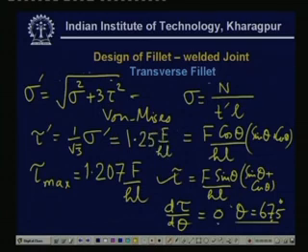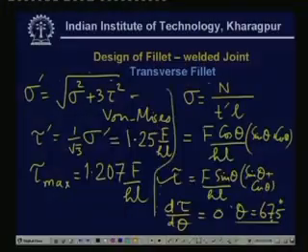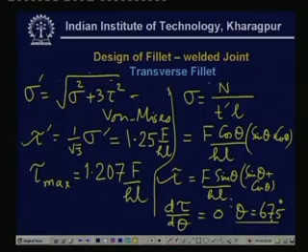So, this I leave to you to calculate, but what is important is that having done all this, what we get is the average value, but it seldom matches with the experimental results. Experiments were carried out with a photoelastic apparatus, and it was found that it is very difficult to find any match, that is, there is practically no match between the strength of materials approach and the reality.